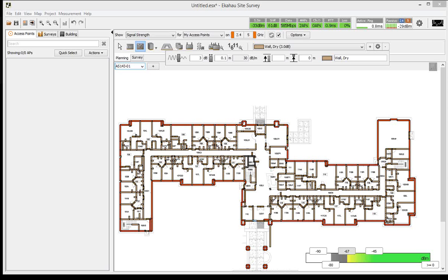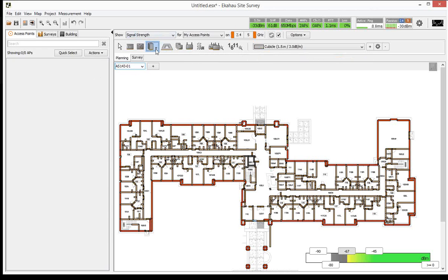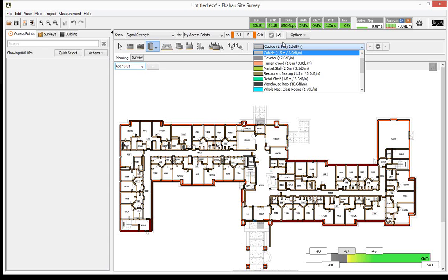So Colin, I'm assuming you are placing the APs fairly high, and then the caravans would be kind of attenuating objects. So how I would deal with that is I would draw the caravans using the attenuation area tool, which is a polygonal tool where you can draw objects on the map.